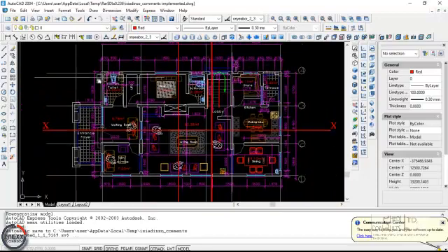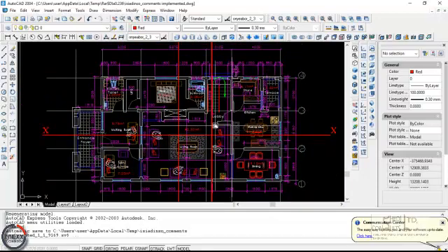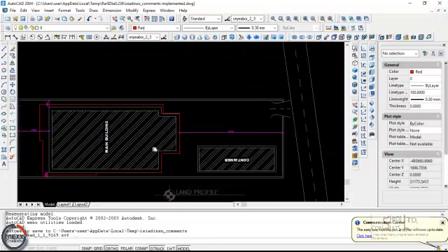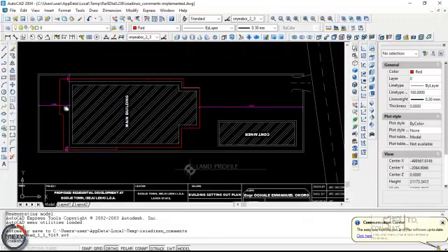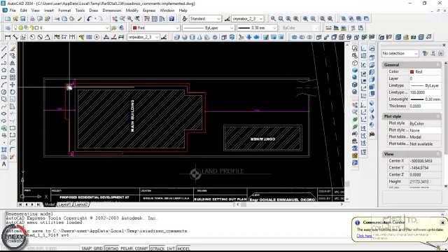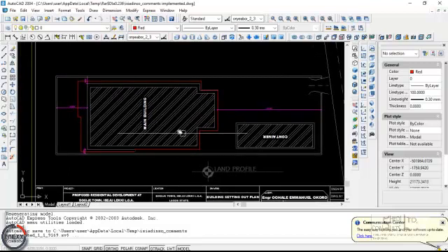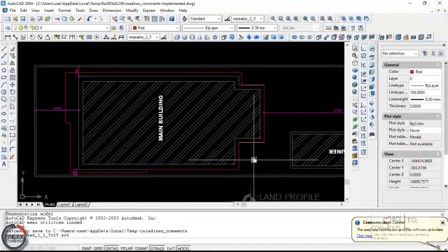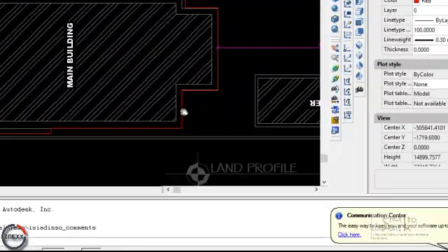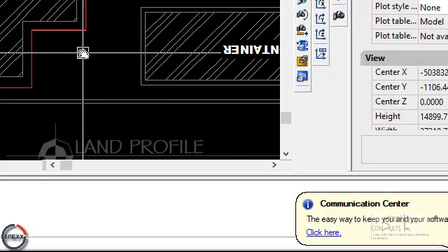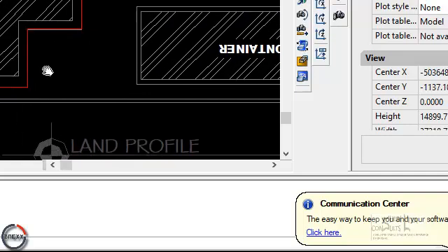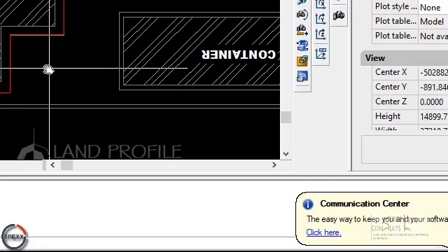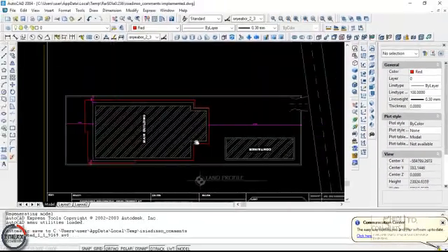We are concentrating on design of the raft foundation for this structure because a visit to the site location showed that the terrain was so bad. You had marshy soil, cohesive peaty soil. By the unified classification system, it was classified that the soil has very high plastic properties, and the bearing capacity is about 75 kilonewton per meter square. So it was decided by we, the structural engineers, to design a raft foundation for this structure.